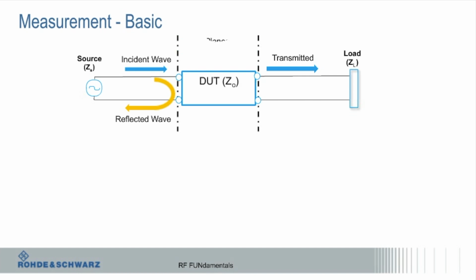And incidentally, my number one thing I support is VNAs, so I like to talk about VNAs. So all this stuff where you see reference planes, and I'll talk ad nauseum about this, so bear with me. After you do a calibration with a VNA, you're really establishing this reference plane.